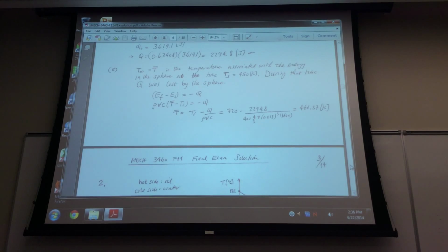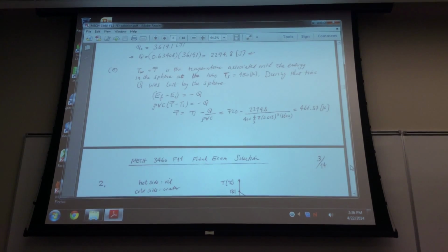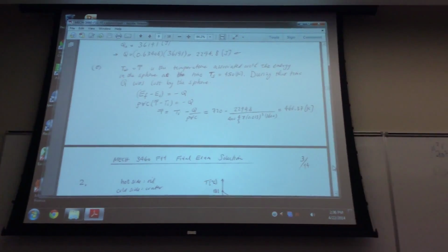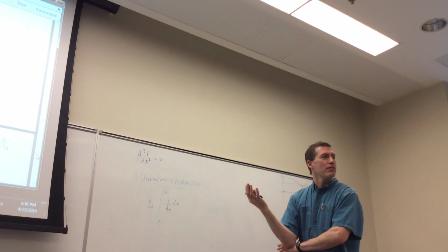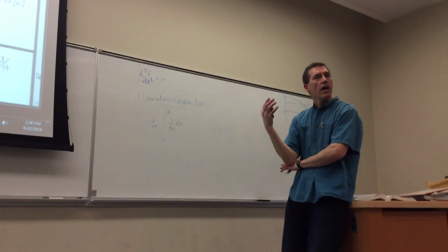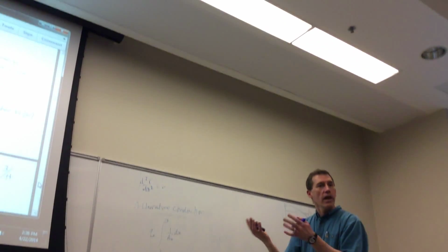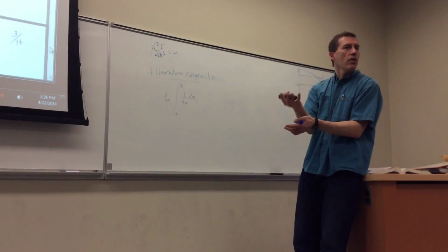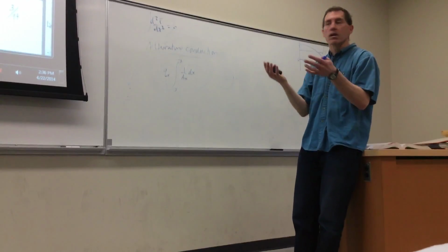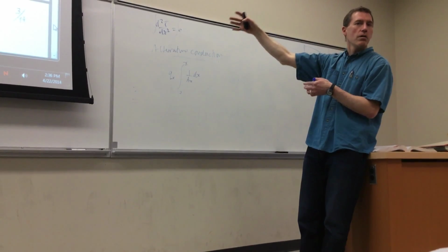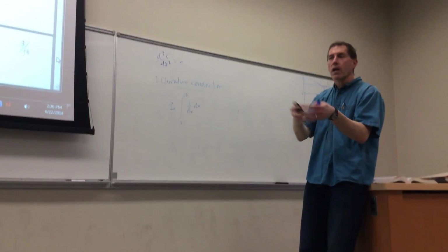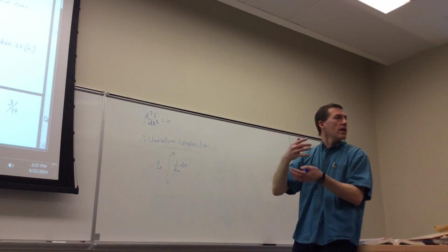Now, should we go through any particular topics? Heat exchangers, everybody's okay with epsilon-NTU? I had a conversation with a couple people in the past. Really it only goes one of two ways, right? You're going to calculate either an NTU or epsilon. It's a 50-50 thing. If you're given the heat transfer coefficient and a geometry, you're going to get NTU, and then you get epsilon, you'll get Q, and you'll get the stream temperatures. If you're given the Q, like we did before, then you can get the epsilon, and you can get the NTU from an equation, then you get the area or the U from that.